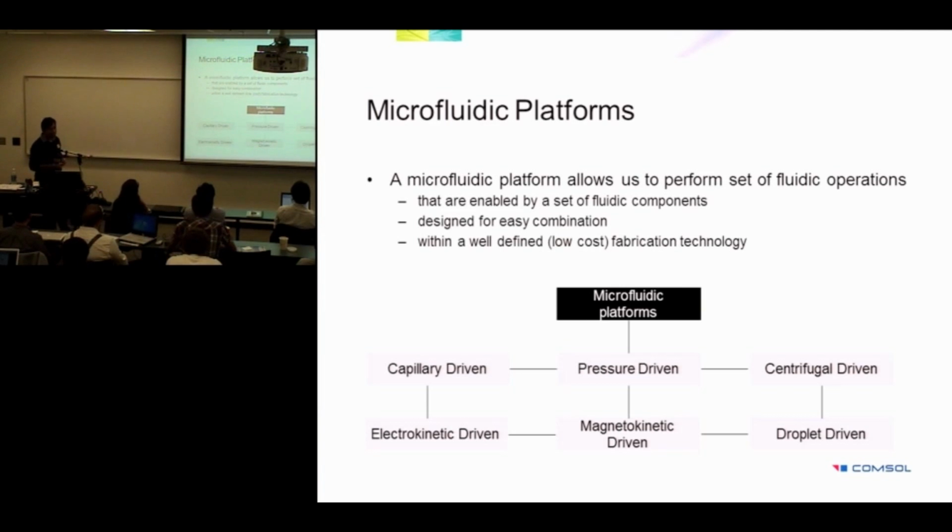There are various platforms available within the microfluidics area which could exploit some of the properties or scaling effects and can be helpful in pumping the fluid through the device for various applications. One could be capillary-driven flow, if there are capillary forces, pressure-driven forces. Centrifugal-driven is also a very innovative technique where you have centrifugal forces. Electrokinetic-driven, where you have electric effects, where the electric field goes up, you have electroosmosis. Magnetokinetic, if you have magnetic particles. And droplet-driven, again more like surface effects or surface tension effects.